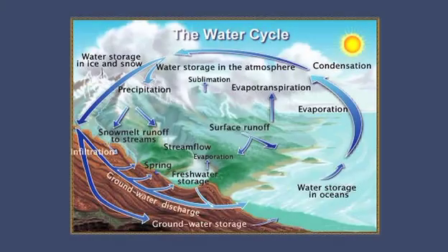The hydrologic cycle describes the continuous recirculatory transport of the waters of the earth, linking atmosphere, land, and oceans. Water evaporates from the ocean's surface and moves inland. Atmospheric conditions act to condense and precipitate water onto the land surface. The return of water to oceans is through surface runoff, driven by gravitational forces.